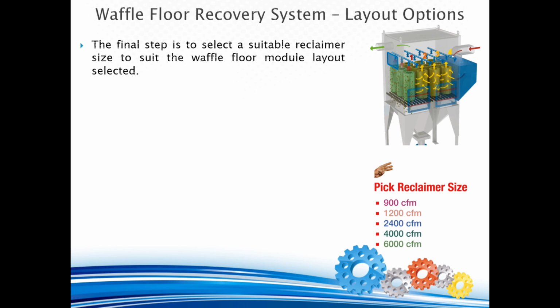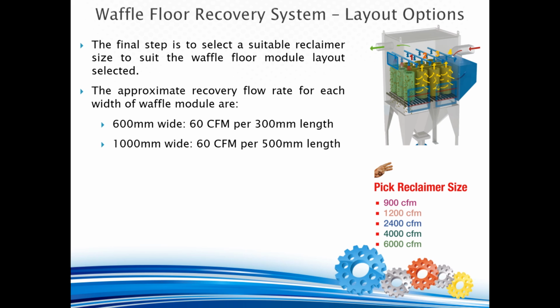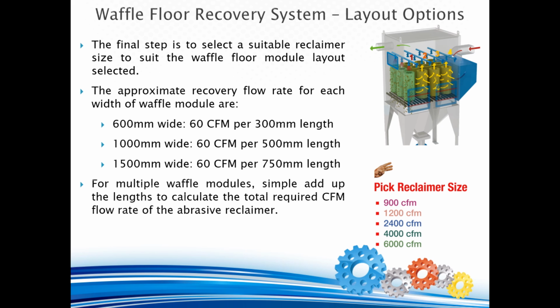The final step is to select a suitable reclaimer size to suit the Waffle floor module layout selected. The approximate recovery flow rates for each width of Waffle module are: 600 mm wide, 60 CFM per 300 mm length; 1000 mm wide, 60 CFM per 500 mm length; 1500 mm wide, 60 CFM per 750 mm length. For multiple Waffle modules, simply add up the lengths to calculate the total required